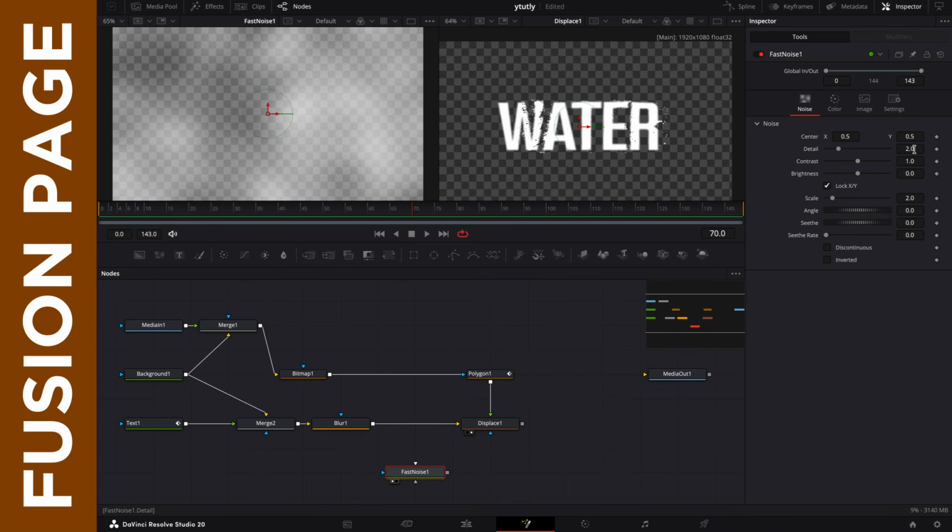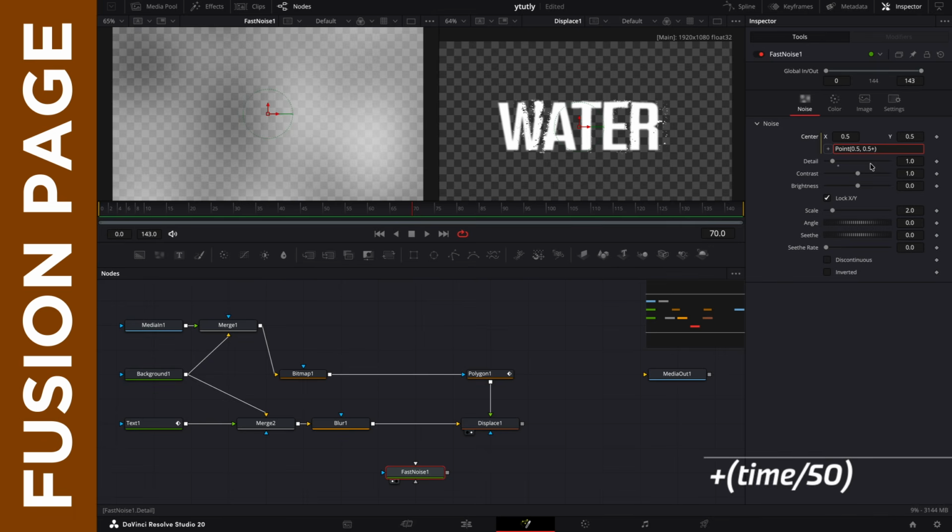I want the detail to be 1. Then I want to right click on this, click on expression. Reason I want this whole particle thing to be moving up like that. So I'm just going to go here and go to the Y value here, which is this second 0.5. I'm going to add an expression to it, say plus, bracket open, time. Time is equal to the count of frames here, right?